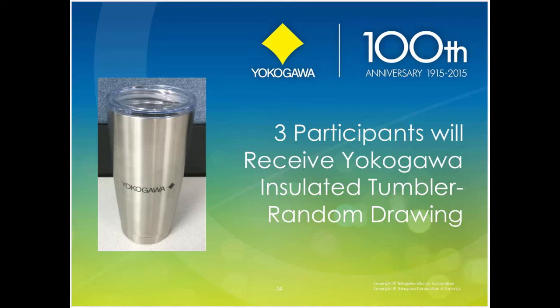So that's the main difference and why, if you can, you should go with an RTD. An RTD can be recalibrated later. As they do drift, you can have it recalibrated and re-verify your Callendar-Van Dusen points, which you can use in your curve matching to maintain your accuracy, even with an older temperature sensor, if you care to go those steps.